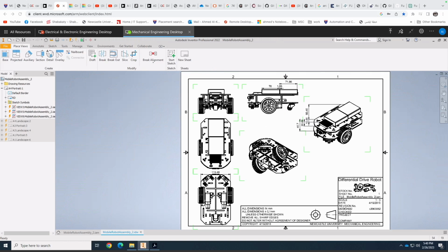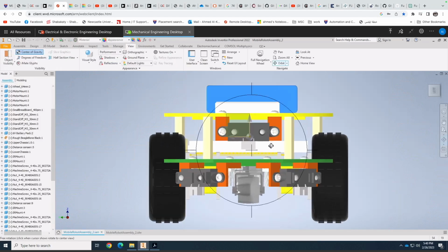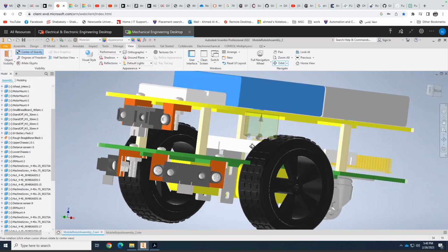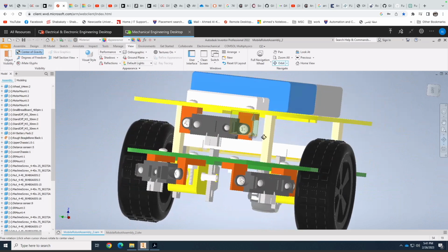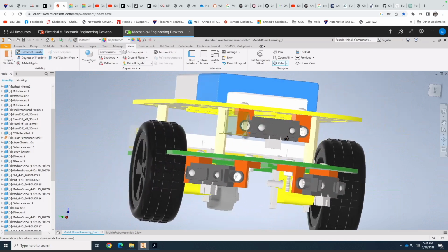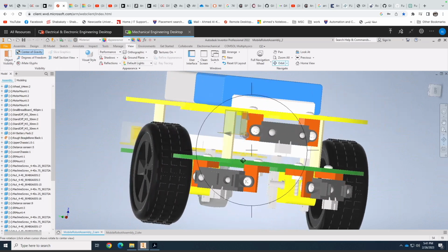I will demonstrate the connection and mounting for each DC motor, and also the 3 distance sensors. And here, the mounting for the distance sensors at the front view of the mobile robot is done by screws and nuts for each distance sensor, and each distance sensor is mounted in each direction, left, right, and front, to measure distance, for the upper chassis and lower chassis.